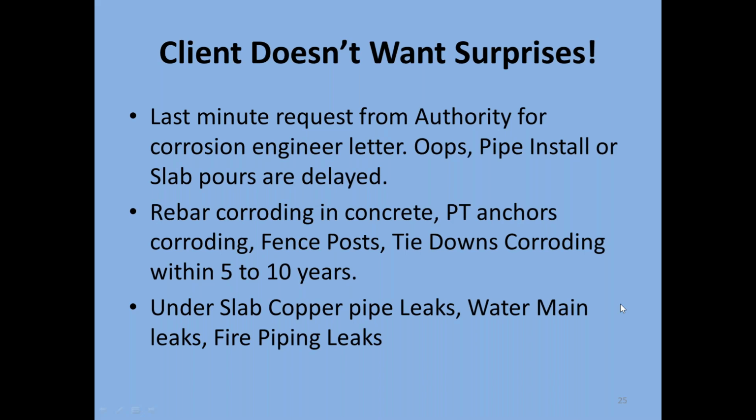So to cover all of those factors, you basically just have to do your homework. That's why we recommend it. The surprises that we've seen from most of our clients is that at the last minute, the city or the county says they want a corrosion engineer letter, a corrosion study of the site, and the client is already practically putting the pipes into the ground.